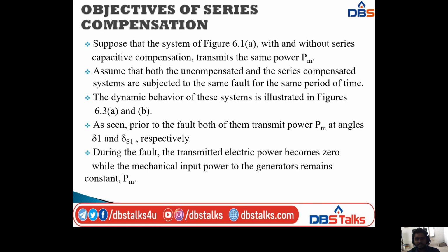Suppose that the system of figure 6.1A, with and without series capacitive compensation, transmits the same power Pm. Assume that both the uncompensated and series compensated systems are subjected to the same fault for the same period of time. The dynamic behavior of this system is illustrated in figure 6.3, A and B.